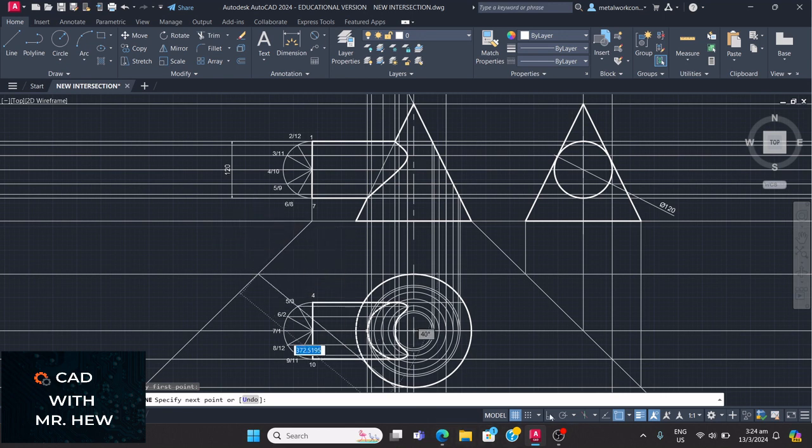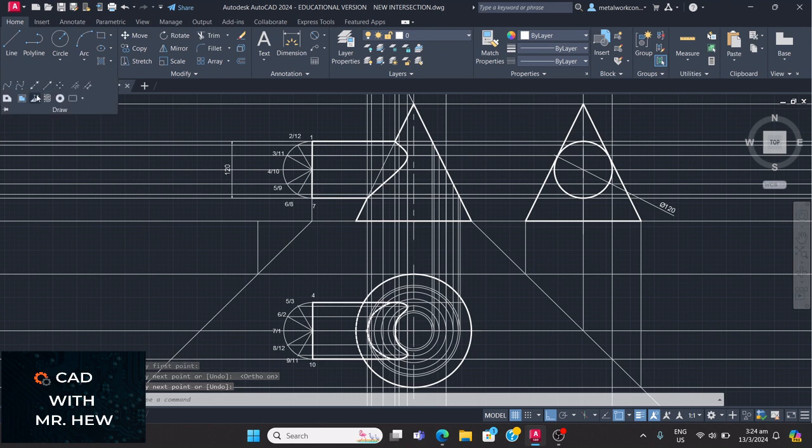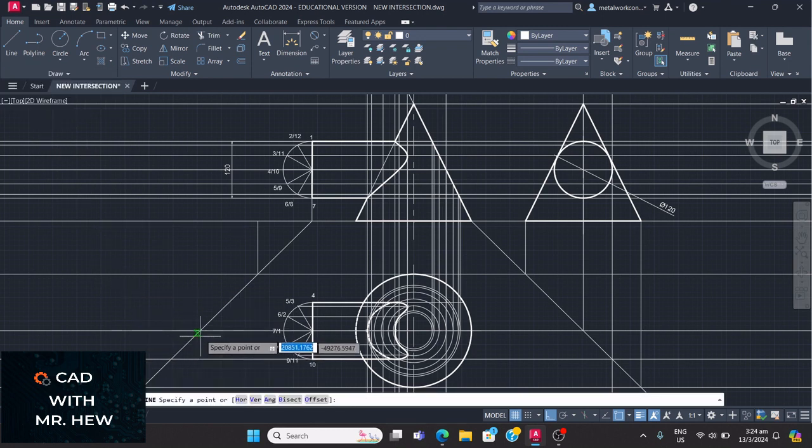I'm gonna turn on ortho, enter. Right, we're gonna carry up the center line. The center line, we can use the X line because it will be easier for us. I didn't carry it at the base because I only need the line up to here, so that is how I'm using the line command here. But you could use the X line, right?